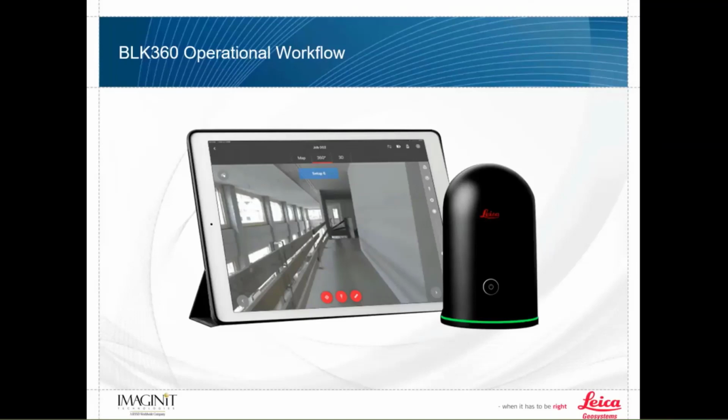But with that said, we're able to use the iPad to collect data and control the settings that I was speaking of just a few moments ago. We're able to control the density of our scans. We're able to control whether we take pictures or not. Are those going to be HDR pictures or not? And we're able to control details like inserting geotags into a scan. Now, we can talk about geotags a little bit later, but these are all things that we're able to do by pairing our Leica equipment here with an iPad.